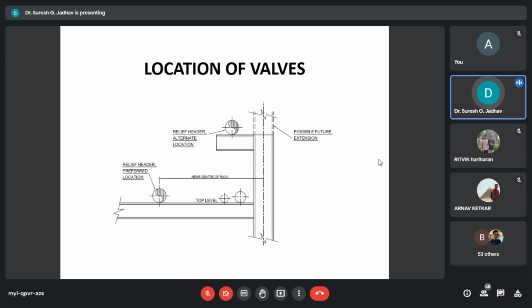In wall locations, we have to consider the orifice flanges near rack columns for access with portable ladders. Orifice runs or after pump can be located near supporting columns. At the plants, various structure elevations are determined by the guidelines of the requirement of header room given above, and the size of the surrounding beams is also taken into account while finalizing the structure levels.